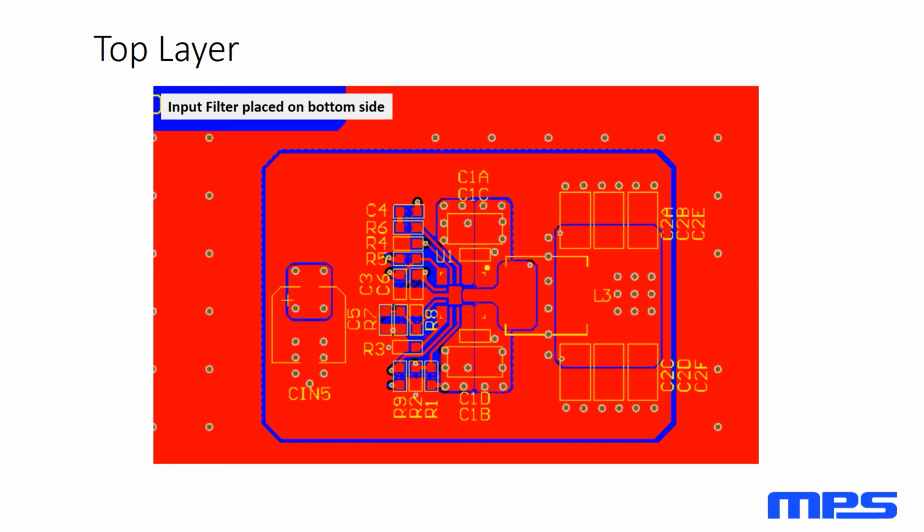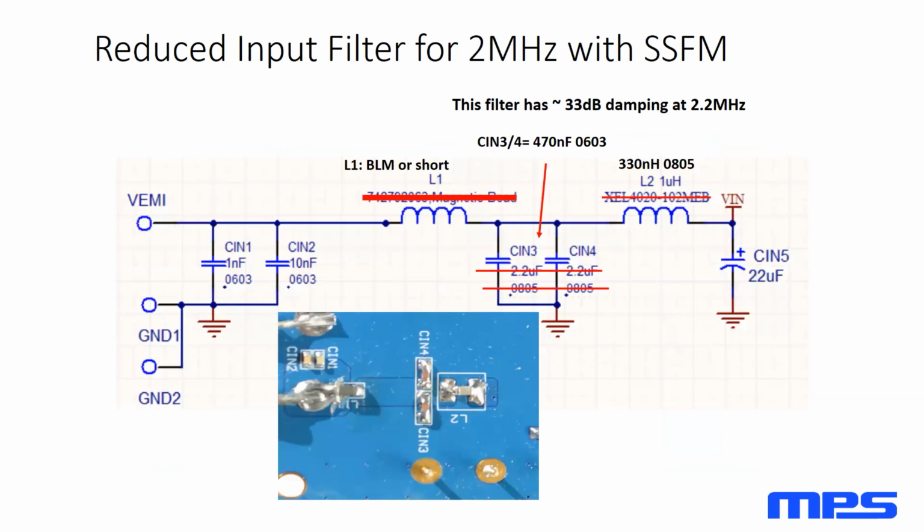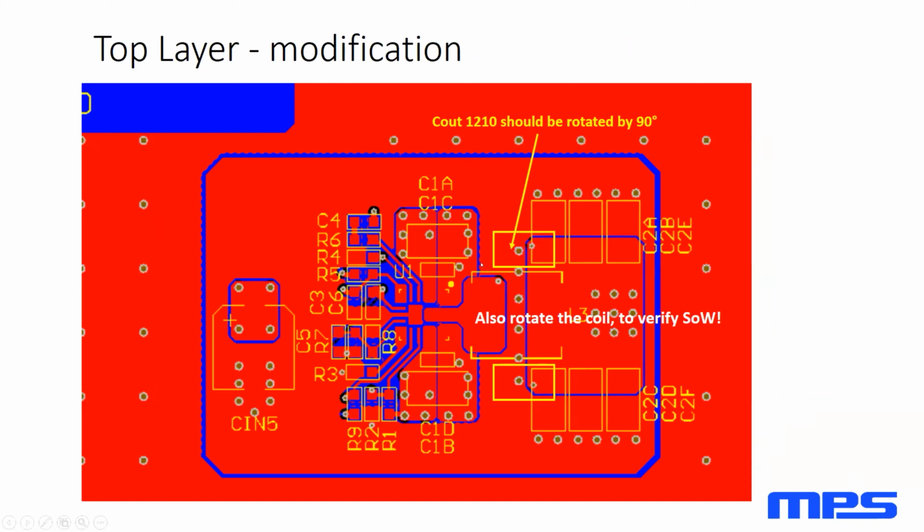I did show that one example where we were rotating the capacitor to try and act as a shield on the switch node. In that case, we maybe wanted a taller capacitor because then it would match more of the size of the inductor and the vertical plate that goes on the inductor for the optical inspection and then the connection. In this case, bigger might be better, but when we're looking at capacitors for frequency, typically smaller is better for the parasitics.